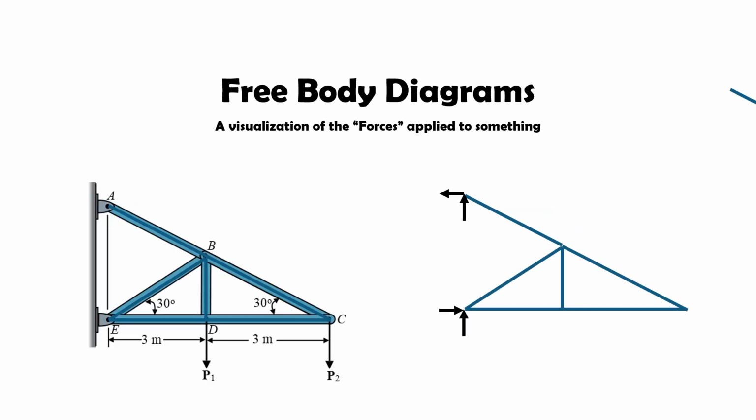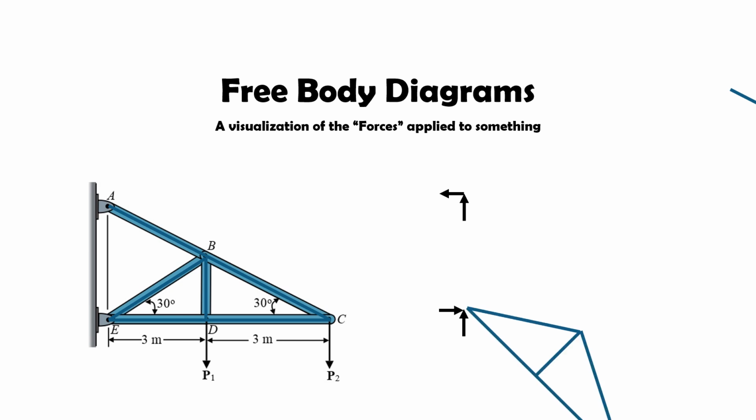We can look at a slightly more complicated system that has multiple ligaments and pin locations. As before, we can represent this as a set of lines with reaction forces at the pins. This time, let's see what happens if we remove one of the rods that holds the system together. Like so. Here too, the rest of the system will rotate and not stay in its original position. This tells us that each of the rods in the truss carries some of the load, not just the pins, and they are required to make the system act as we would expect.